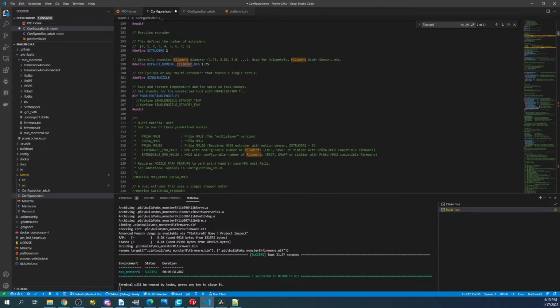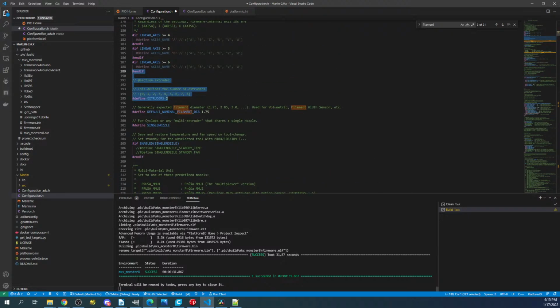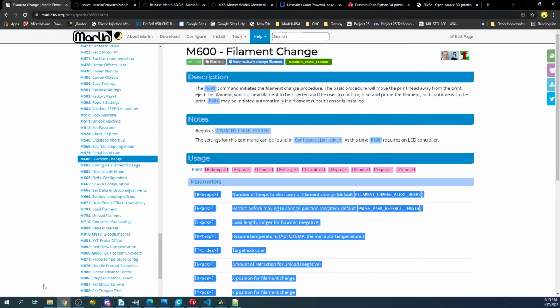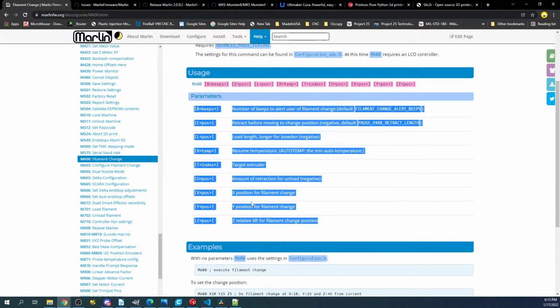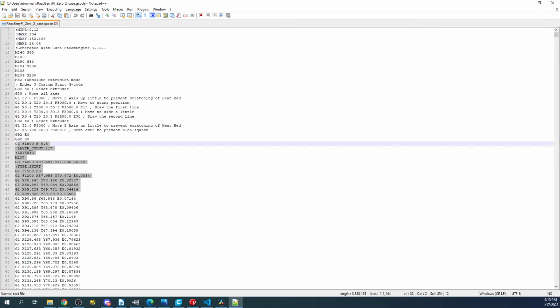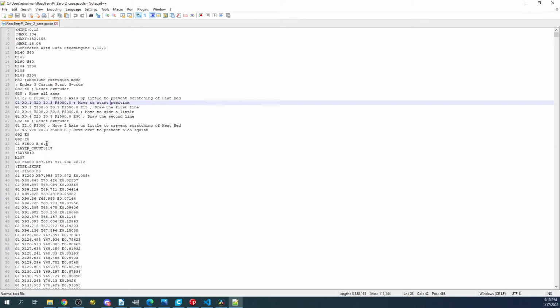So, as you can see, the multi-extruders right here, that's some more functionality that we can find with G-codes. But you can also test your printer by creating your own G-code file. Like if you want to see if it homes correctly, you can actually just take like this portion down in here where it says G28, and that's going to be your home all axes. If you wanted to test, for instance, that it's setting temperature, you could use the information up here.